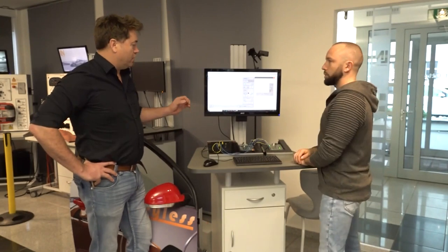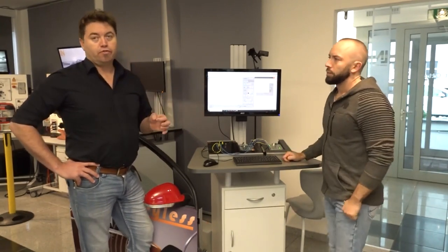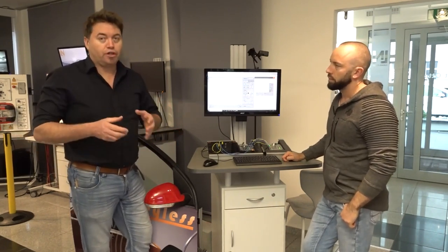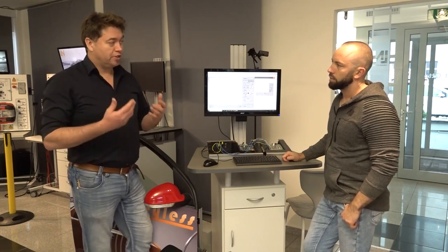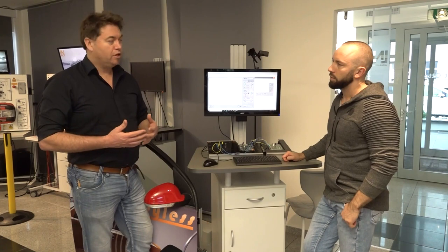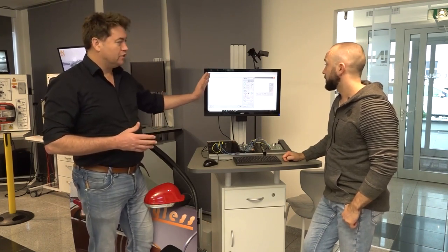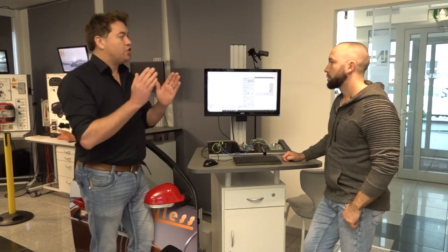The thing you've got to realize is it comes down to diagnosis. You've got a vehicle that's not operating correctly. The lights aren't working or a certain door is not working. In a lot of cases, vehicles are getting flat batteries because the CAN bus system is not going to sleep. So it's not necessarily about the signal. I haven't had many cases where the signal changes.